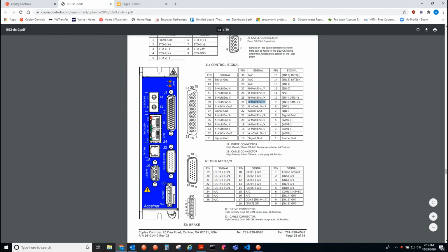And then likewise for axis B, S0 and S. We're going to be using the S0 channel for both axes, because when the fault is active, the S goes low and the S0 goes high. So S and S0 are obviously inversions of each other.